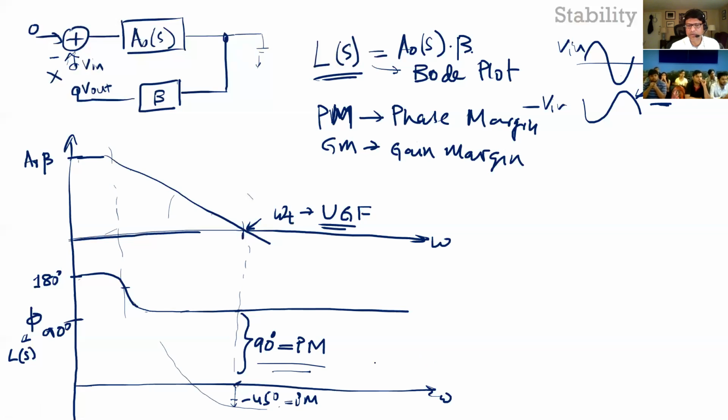And this is a useful technique because, as I said, your root locus or Routh criteria or Nyquist plot will just tell you if it is stable or not. But it could be marginally stable. And the way we know if it is marginally stable or not is from this phase margin number. Let's say, for example, this was 12 degrees, then it is very close to being unstable. If it is 90 degrees, it's very stable. So usually we want 45 degrees plus to be what's called a critically damped system. And we'll talk more about this.